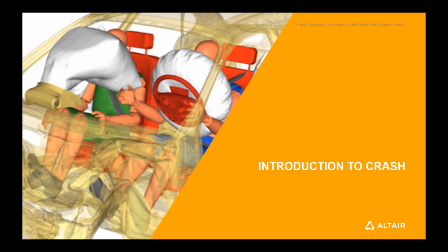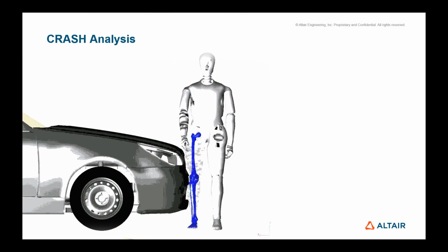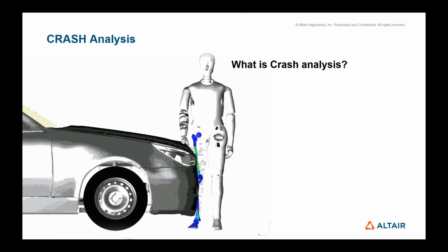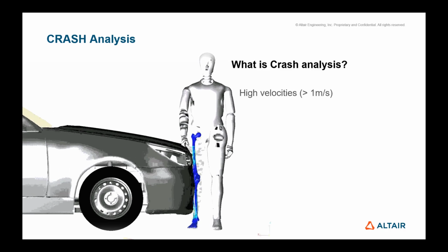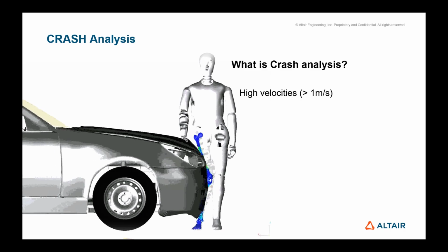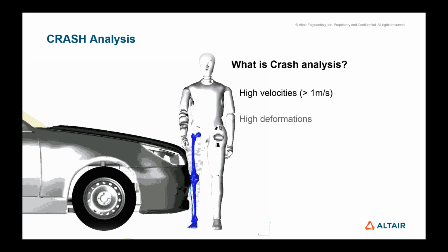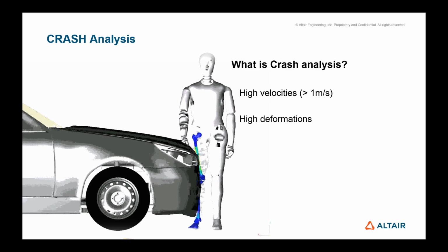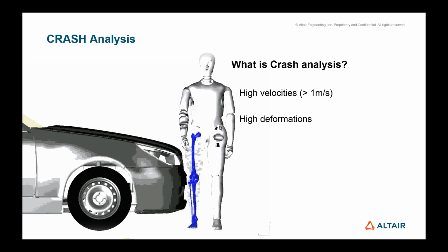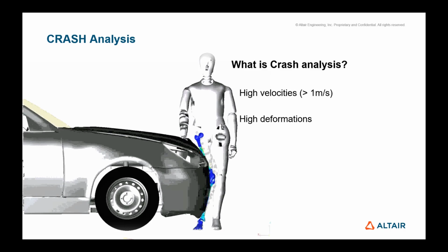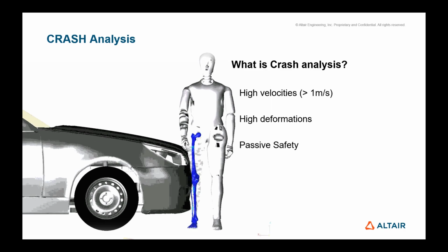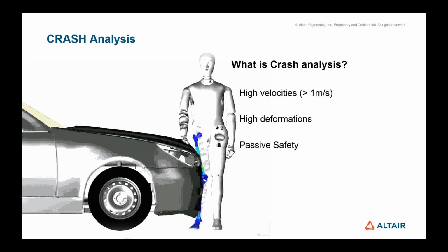So let's start with what crash analysis usually covers and why people are doing crash analysis. Crash analyses are basically impacts at speeds higher than 1 meter per second and usually lower than 100 meters per second. In standard vehicle development, they often also cover all cases leading to high deformations, and generally all analyses related to passive safety.